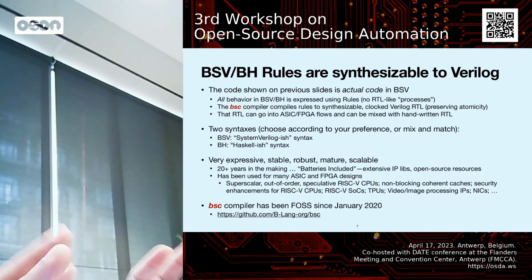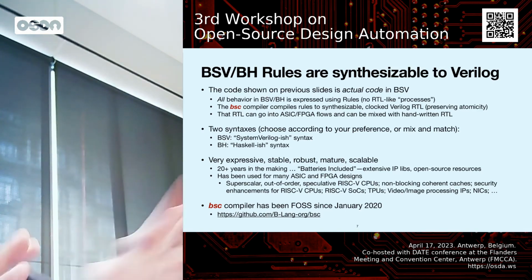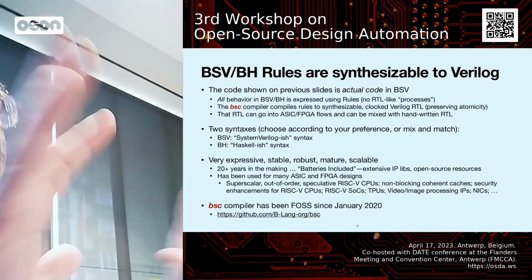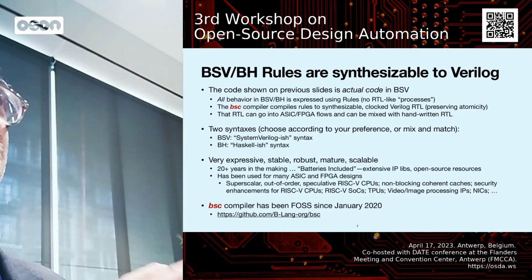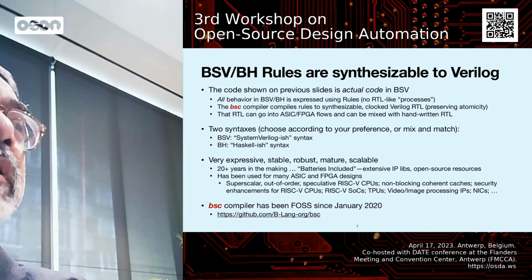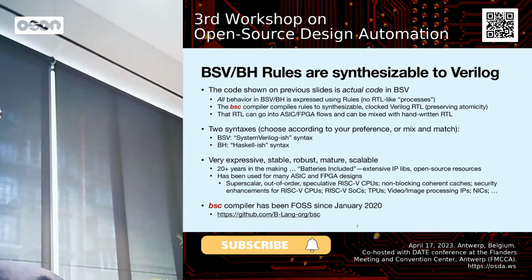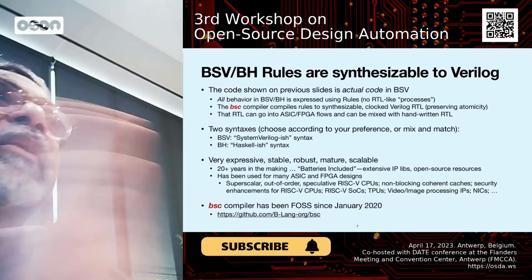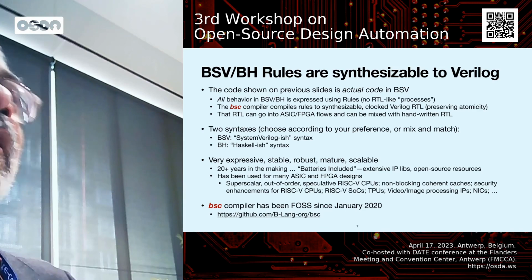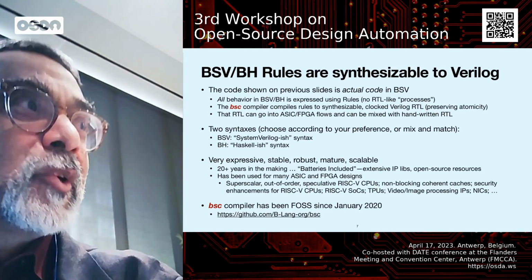The tool is not making any innovation except local combinatorial optimizations. Generally, the overall structure is designer specified, whereas in HLS, the tool has an architecture and it has knobs by which you can adjust details of that architecture by and large. So that's one major difference. We sit very much in the Verilog, SystemVerilog, Chisel camp, as opposed to HLS.